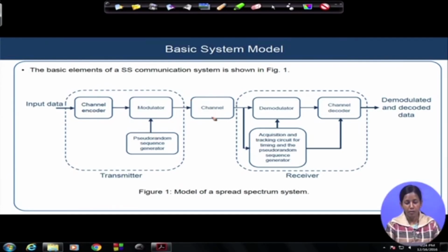If it is a wireless channel, we know a lot of channel encoding techniques, for example the convolution code, the LDPC code, or the concatenated codes where the RS and convolution codes are combined, and so on.